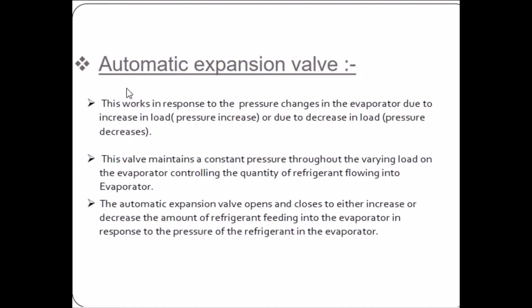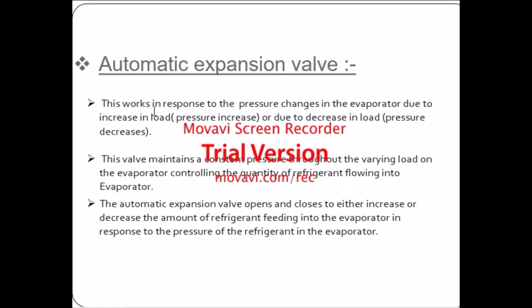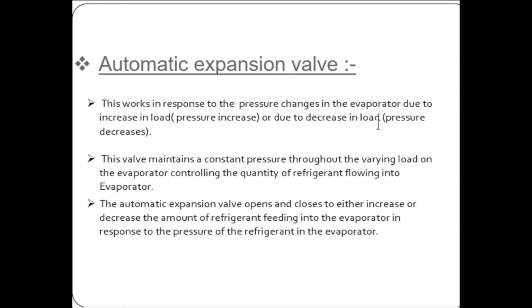So the automatic expansion valve works in response to the pressure change in the evaporator: due to an increase in load, pressure increases, or due to a decrease in load, pressure decreases. So this automatic system will control the needle. Needle means the diaphragm.